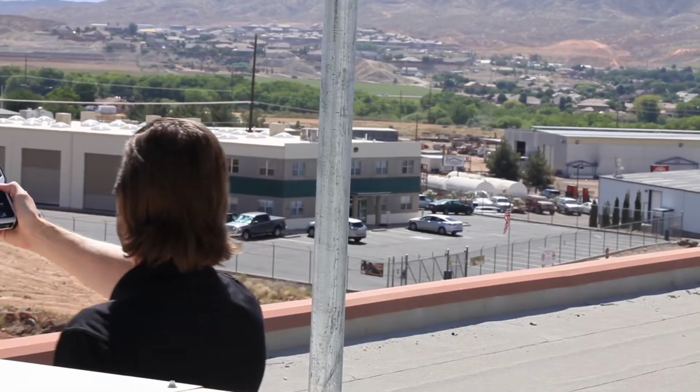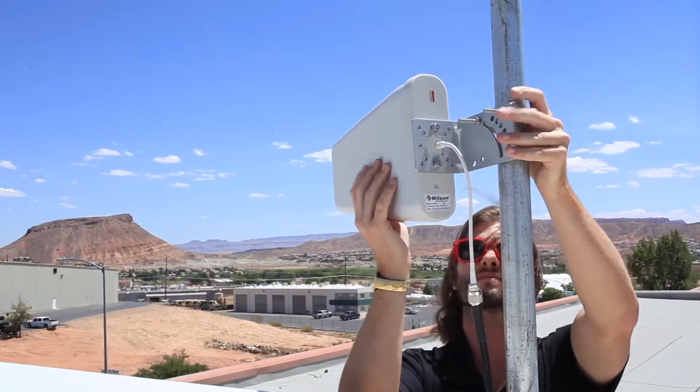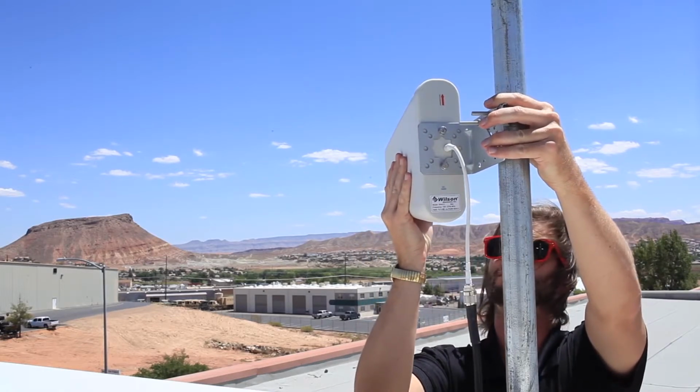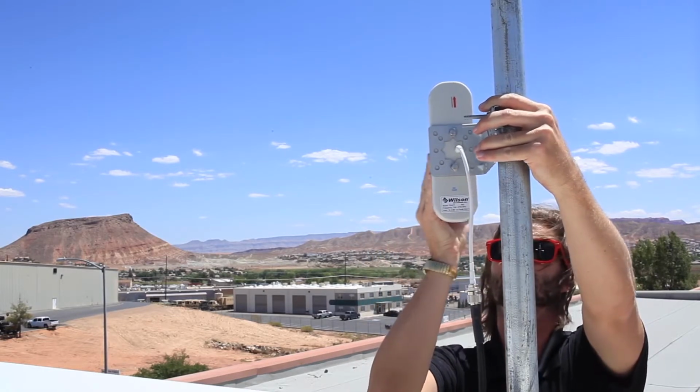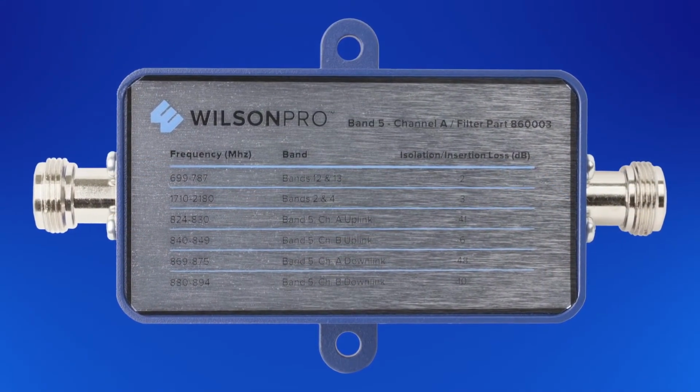To solve for this issue, you can find a location on the roof with less signal, use a directional antenna to aim it away from the cell tower, or you can experiment with shielding the antenna to weaken the incoming signal. Filters may also be a great choice to help you alleviate this problem.